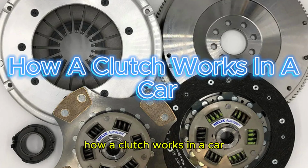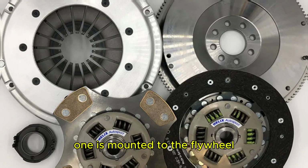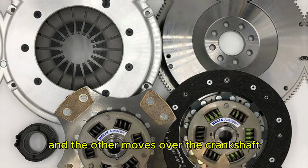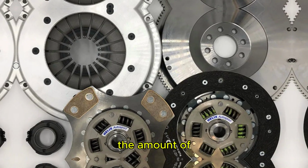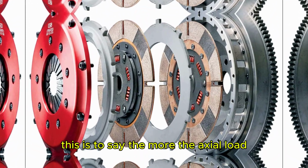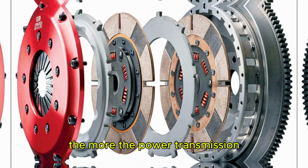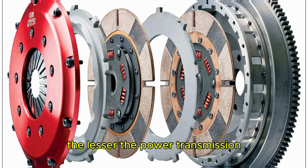How a clutch works in a car. The clutch consists of two different plates. One is mounted to the flywheel, and the other moves over the crankshaft. The amount of torque applied determines the amount of axial load that is applied to the friction disc. This is to say, the more the axial load, the more the power transmission, and the less the axial load, the lesser the power transmission.